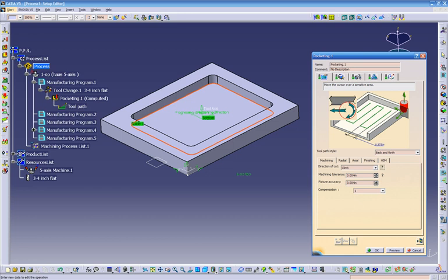See, this is the rotation of the end mill. The end mill rotates clockwise, and it's moving forward this way. See the arrow going this way, and the tool rotates this way. So everything is climbing. I'm pretty sure all the programmers out there know that most of the programs need to be climbing. Rarely do we find programs where we get a nice finish using conventional. So I very rarely use conventional. I always leave this on climb all the time. I never change it.